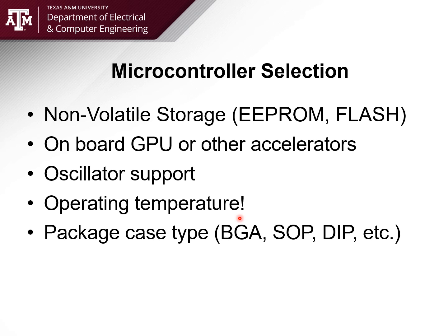Same thing, if you've got something that supports up to 70 degrees Celsius and you end up working in an environment that's pushing 80, 85, 105 Celsius, which does happen. Think automotive. That becomes a big problem.